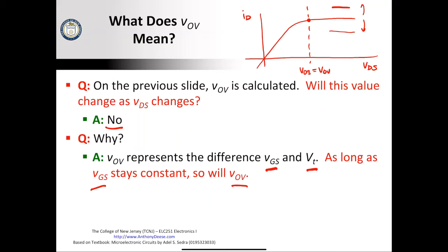So we have to move somewhere along this VI curve. This is 100 microamps. This down here would be 50 microamps. So that would put us at that point right there. And you can see very clearly from this picture that as we move towards this second point, we will be in the triode region of operation.